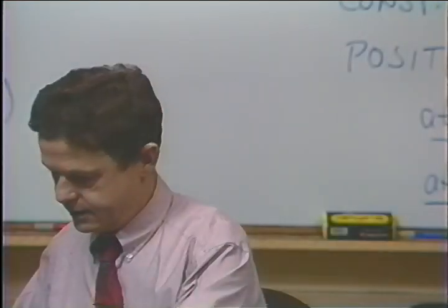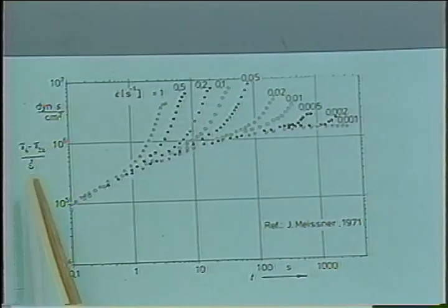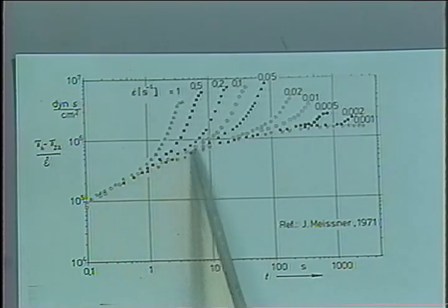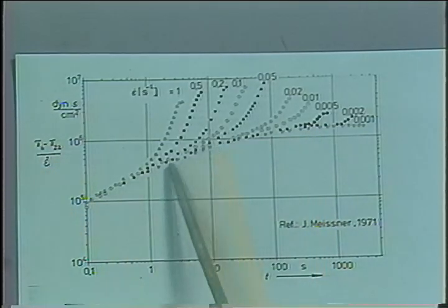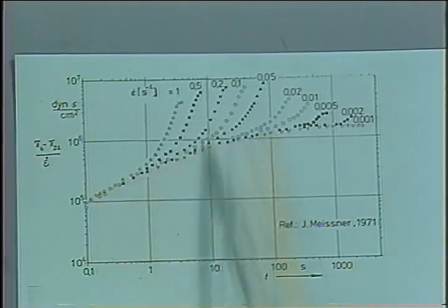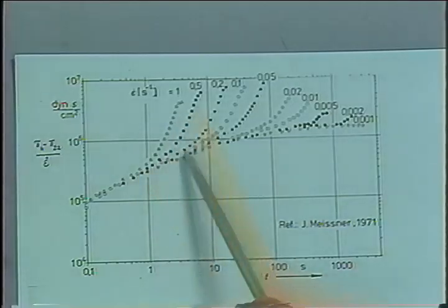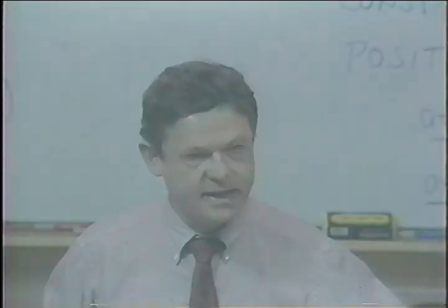I showed some of it. Oh, where did we have those? Here, this is a typical data set. The material function, the first normal stress difference divided by the extension rate, as a function of time during the startup experiment. The stress is increasing in time. Now, by dividing with the extension rate, all the data fall together and coincide with the viscosity, and at some time, there's a deviation where somehow the stress grows extensively. Okay, so those data are taken on melts.